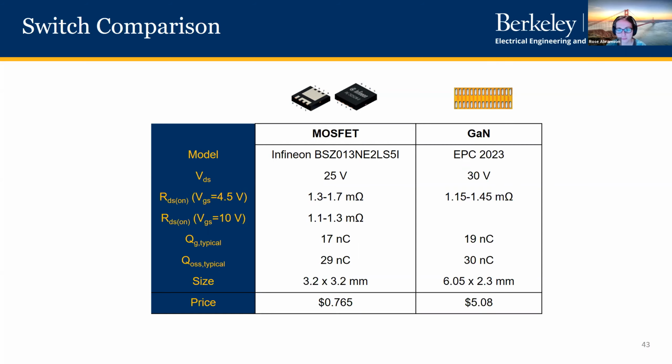Sure. I guess I would say to do a lot of simulation and calculation before you build it. But in general, it's good to make several different boards that you can test different variants on, because we do try to do a lot of optimization for efficiency. So you might be swapping out inductors and capacitors.